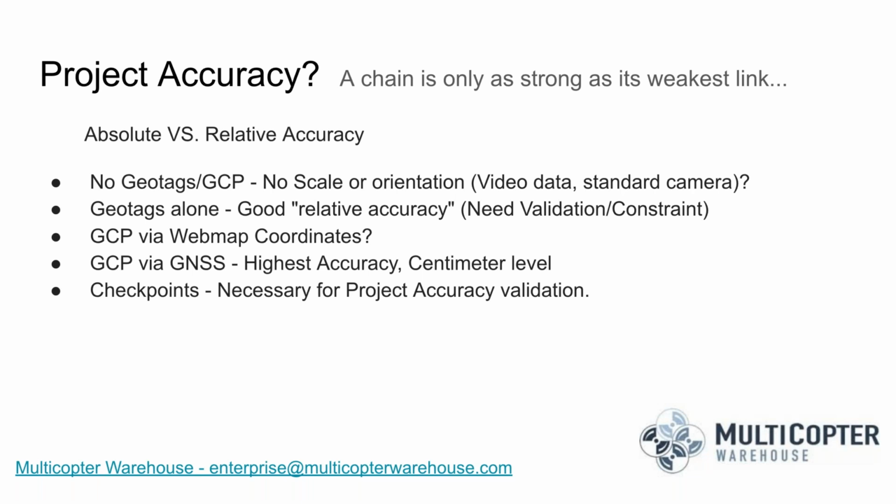from the drone. And ultimately, if you're looking to get your data correlated very closely with data from, say, Google, you can actually go into Google and create some waypoints, if you will. They're not really waypoints; they're just points on the map, and you can extract coordinates from that and use that to geo-reference your image to make it more closely match up with Google imagery.